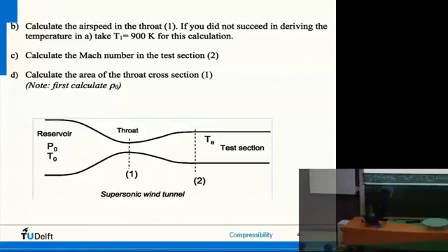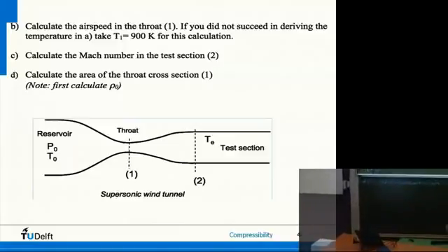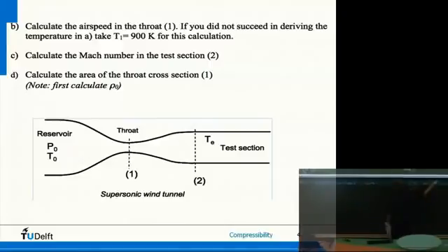So this is constant. And what is it equal to? It's equal to the mass flow. And you can check it, because we have rho, kilograms per meters to the third, area, meters squared, v, speed, meters per second. So what is the dimension of this? It's kilograms per second. So how much kilograms of air go through this area per second? So it's the mass flow.